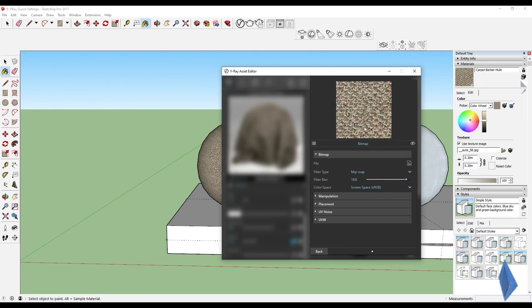Why is that happening? It is because the blur actually picks up the 3D-ness in the whole thing. All right. And how VRay works is basically where it sees light color, like white and the lighter colors, it thinks of that being up, and wherever it sees the dark color, it feels that to be a dip or a depth inside. That's basically how it picks up the whole thing, for it to look 3D.